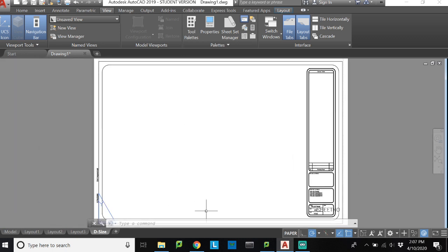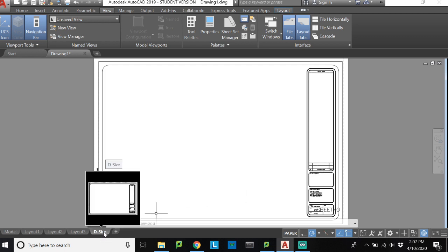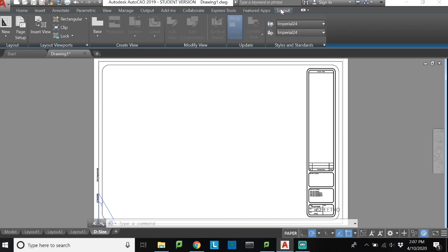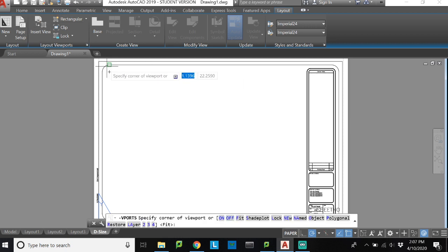So FYI. Now, as soon as you get this drawing up and you've filled out this piece the way that you want it, what I would suggest doing before you do anything else is go into Layout, up here in your Layout tab, and click on a rectangular view.